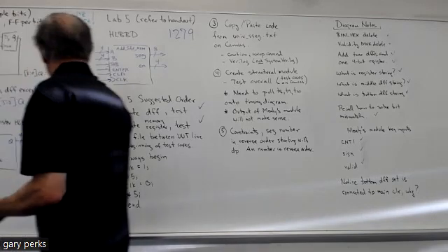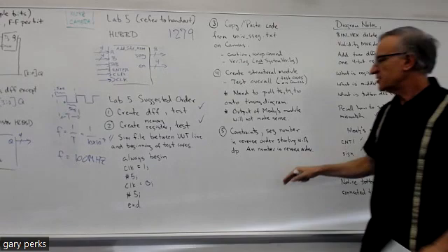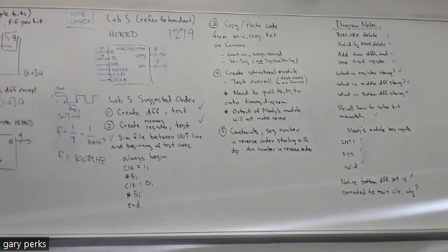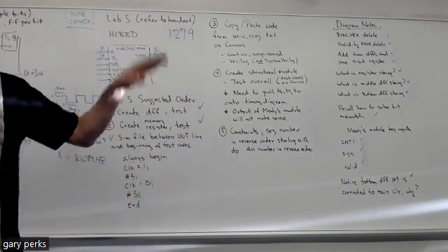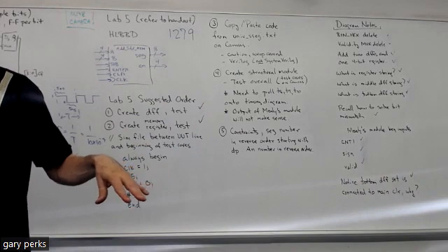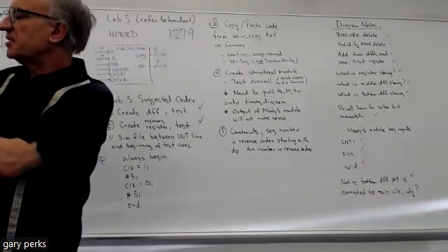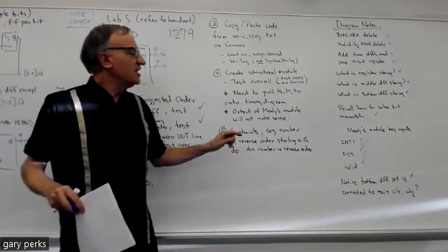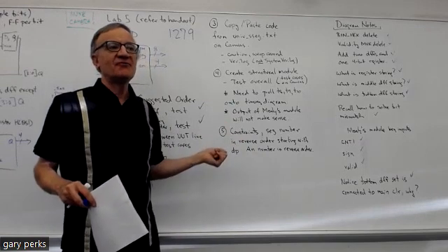Okay. All right, the last thing, unless you have questions, is when you do the constraints file for lab 5, and remember lab 4 was the first lab that you were dealing with the 7-segment display, and I gave you a handout, hopefully you still have it or you have a picture of it, that shows you how to number the segs and the AN. Okay, everybody know what I'm talking about? Okay, well, because of how Dr. Mealy designed this time multiplexer, when you do the constraints file for lab 5, number the seg and the AN reverse of what you did in lab 4.